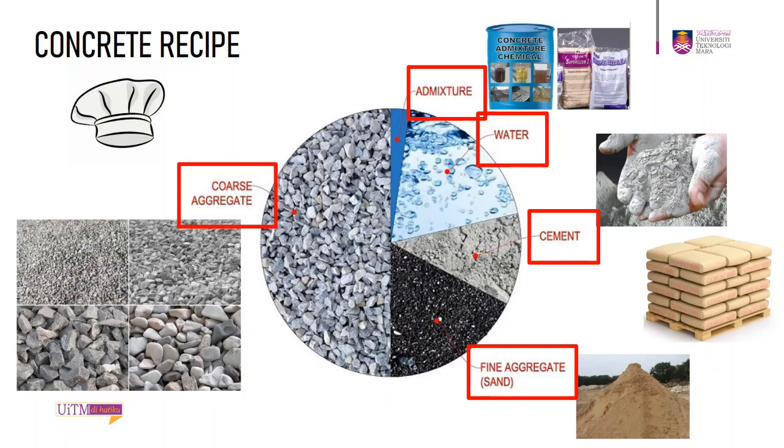For increased workability and for economy as reflected by use of less cement, the fine aggregate should have a rounded shape. The purpose of the fine aggregate is to fill the voids in the coarse aggregate and to act as a workability agent. The strength of the bond between aggregate and cement paste depends on surface roughness and surface porosity of the aggregate. Aggregate with rough and porous texture increases the bonding between aggregate and cement, and may increase compressive and flexural strength compared to smooth surface aggregate.